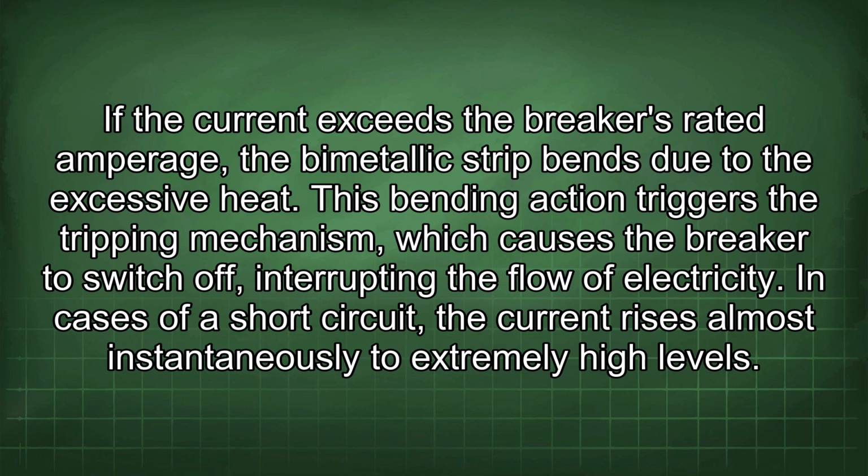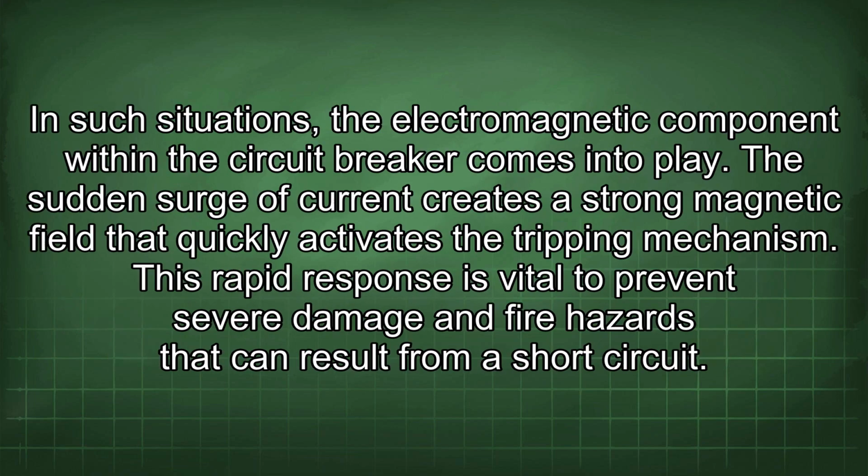In cases of a short circuit, the current rises almost instantaneously to extremely high levels. In such situations, the electromagnetic component within the circuit breaker comes into play. The sudden surge of current creates a strong magnetic field that quickly activates the tripping mechanism. This rapid response is vital to prevent severe damage and fire hazards that can result from a short circuit.